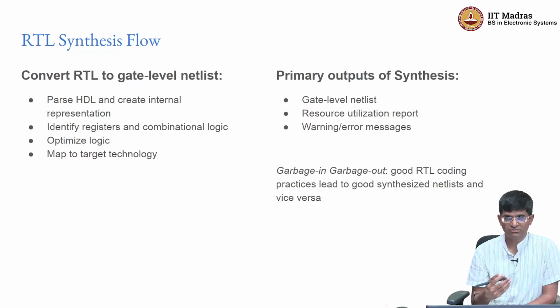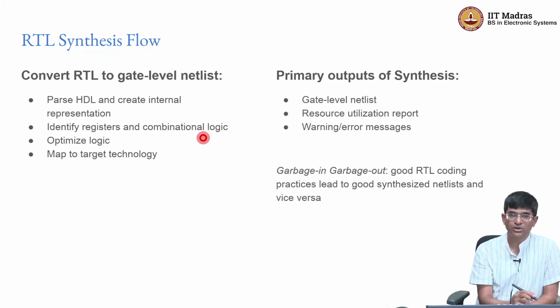Synthesis essentially refers to the process by which there is a program, a compiler, which takes the Verilog RTL that you have written and converts it into another format. This sounds exactly like what a C compiler does. It takes your C code, converts it into an intermediate representation, does some kind of optimizations on it, finally generates assembly language and then machine code for you. In this case, I write Verilog code or VHDL, and there is a compiler that parses it and creates an intermediate representation. It identifies registers, combinational logic and so on inside this code, and does a lot of optimizations. Whatever we would have done with Karnaugh maps and various other kinds of Boolean optimizations are automated away in there.